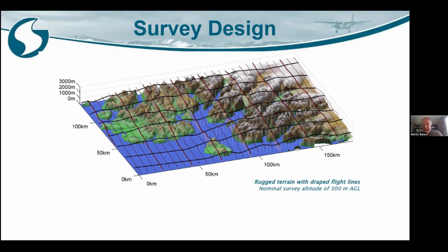The gravity meter doesn't have that problem, but it does have a slow change to it, so it doesn't need as many control lines to correct that. It's relatively easy to correct for. You can get nice profiles from the EM along those lines, but you can't actually level EM using control lines because of the coupling effect I mentioned.